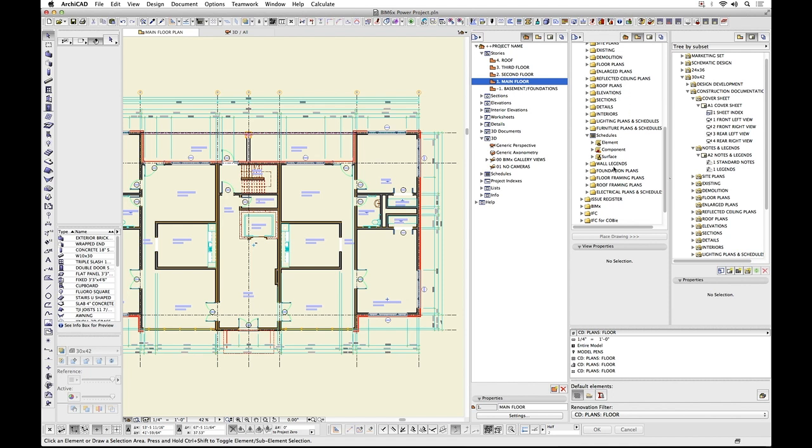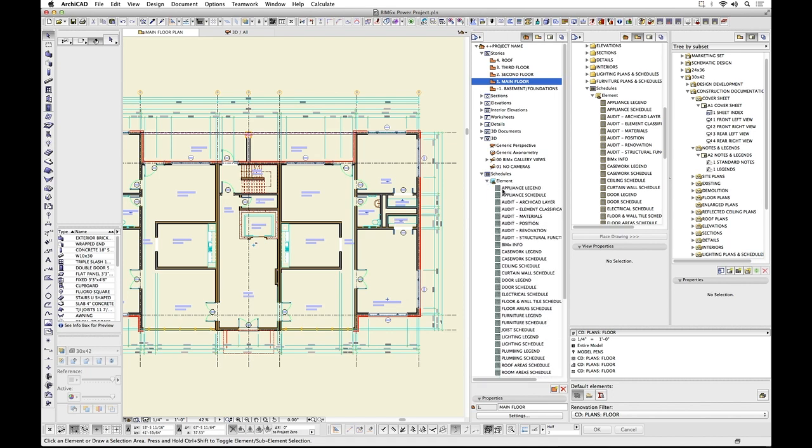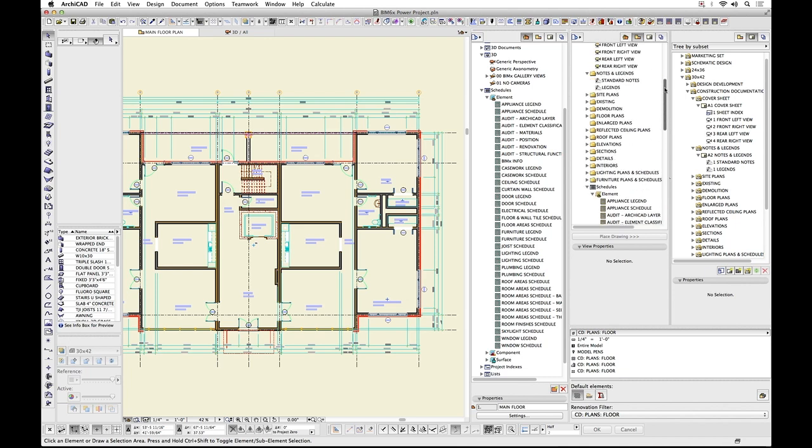It's also important to note that if you do have a cloned view and you delete it, it will delete all of them. So they can be a little bit dangerous. We only use them for schedules really, because with schedules you usually want to clone and want a copy of every single schedule that you've made, and they all want to have the same settings. So the settings that we use have a lot of consistency.